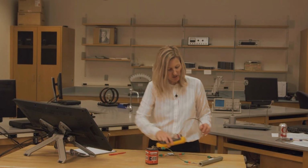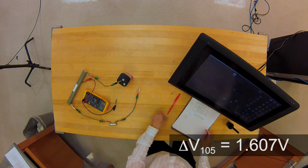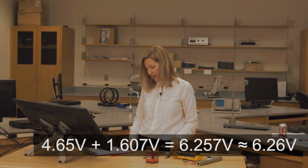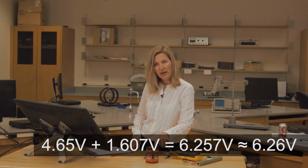Now we'll measure the potential difference across the 105 ohm resistor. 1.607 volts. So if we add the two readings across the resistors together, we get 6.26 volts. And when we measured the potential difference across the battery, it was 6.26 volts.